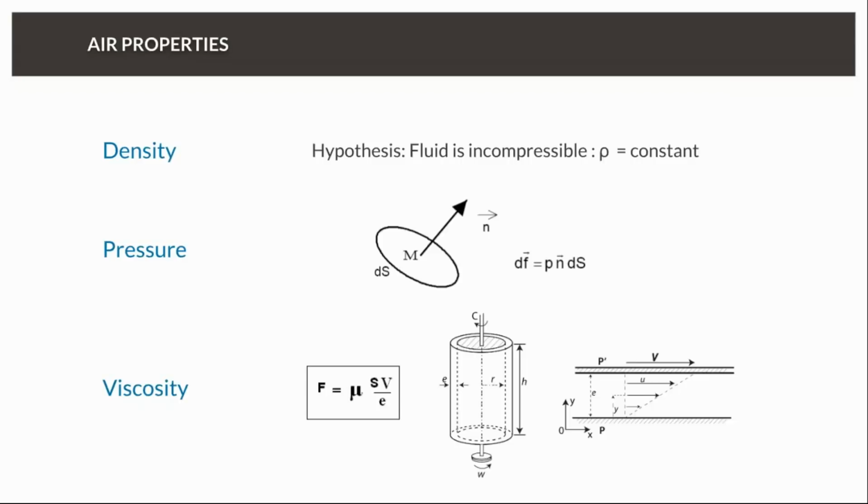If, for instance, you put a cylinder, you fill it with a viscous fluid, let's say oil, and you put another cylinder inside. When you start to rotate the internal cylinder, due to the viscous forces, you will see that if you don't hold the external cylinder, little by little, this cylinder will start to move. Or you would need to apply a torque to hold it fixed. That will depend on the speed of the rotation and the viscosity of the fluid.